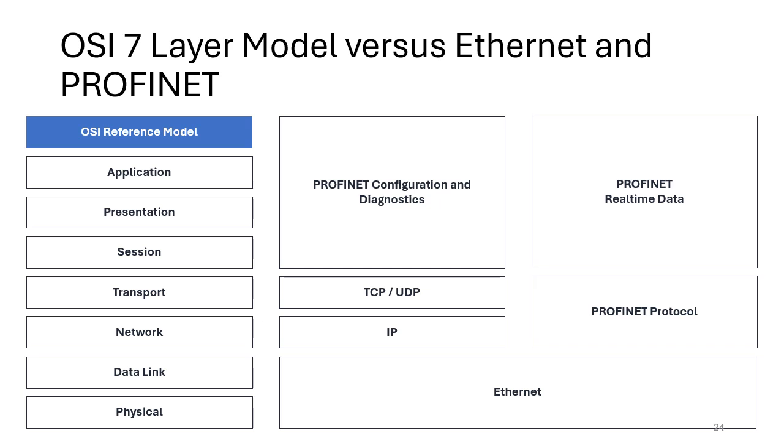And typically, RT is used for standard I/O, discrete in, discrete out, analog in, analog out, where you have a high-speed cycle. But the IRT is used for devices which need even higher cycle times. So typically that would be for servo motion devices. But you can see how both networks, both operating on Ethernet, correspond here to the OSI 7-layer reference model.